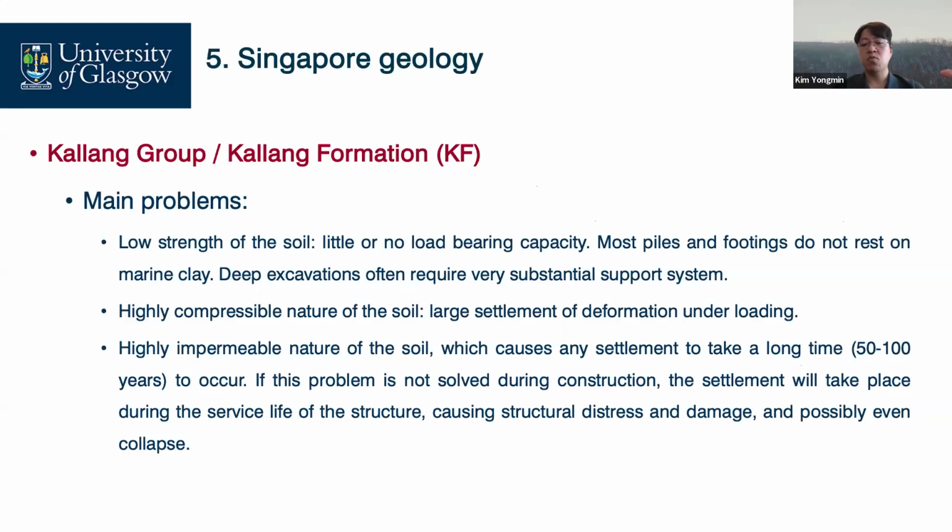So deep excavation work requires very substantial supporting systems. So Singapore engineers used to adopt a permanent substantial retaining wall. It's called diaphragm walls. All MRT stations adopted the wall to support the low strength soil bodies.